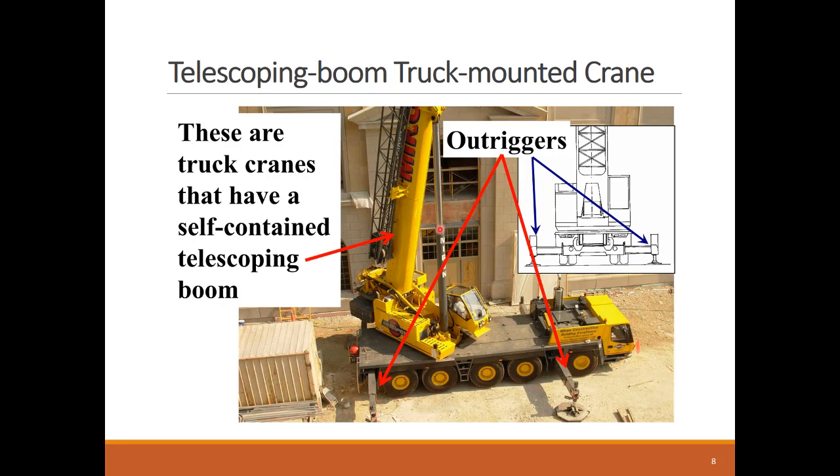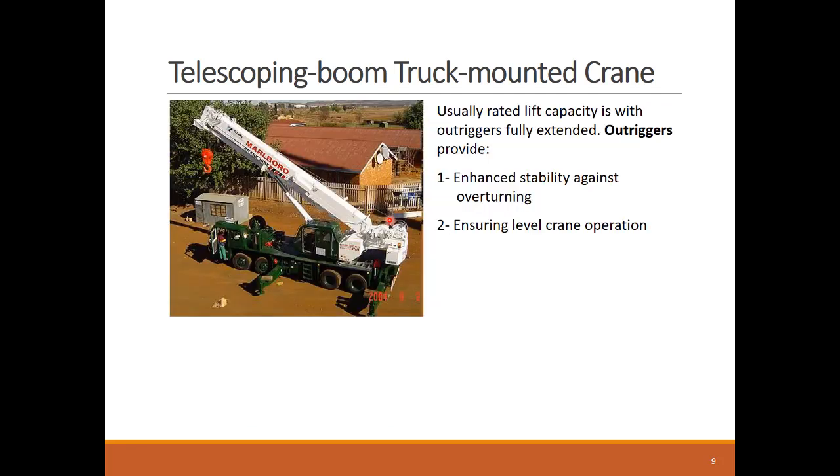The crane operator is responsible to make sure that the surface below the outriggers is strong enough to support the weight of the crane and the lifted load. Also, there should be enough space around the crane to open the outriggers and have them supported on reliable and leveled surface. Once the crane outriggers are secured, the crane operator extends the telescoping boom and performs the rigging operation.